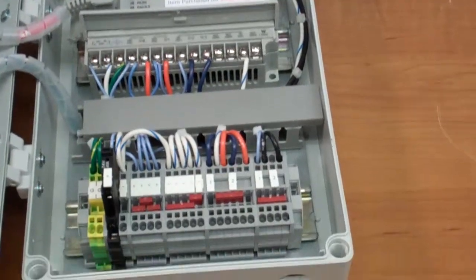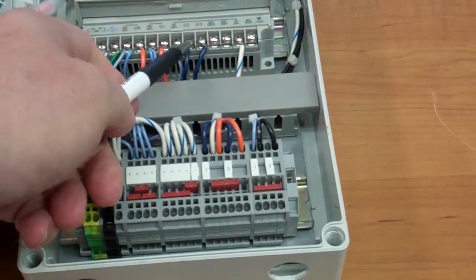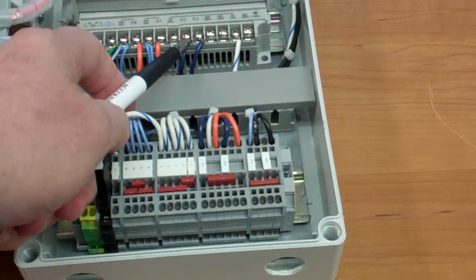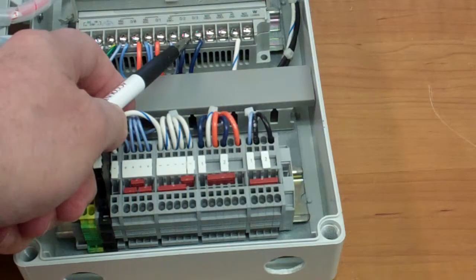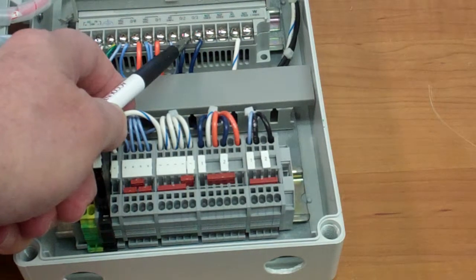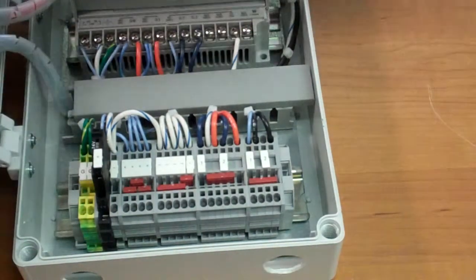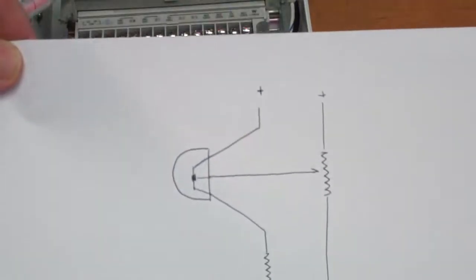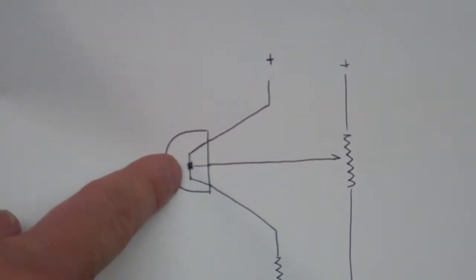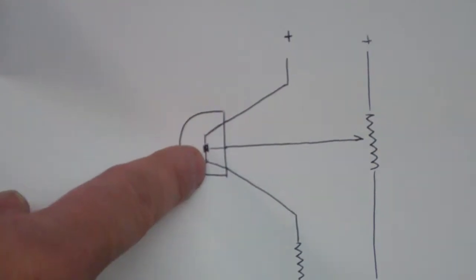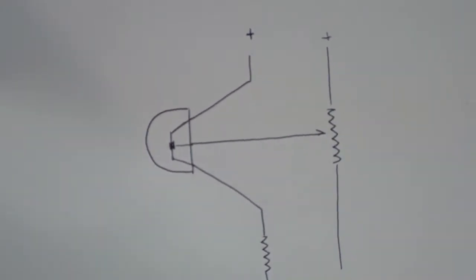We began selling this product line assuming we'll be using low power valves for the air, half-watt valves. These FETs would be fine for that. We ended up using regular 24 VDC 10-watt valves. These FETs will eventually burn out. Again, the burnout is when that junction right there just wears out due to electric flow. It just burns out. But it burns closed, not open. It burns closed in this case.